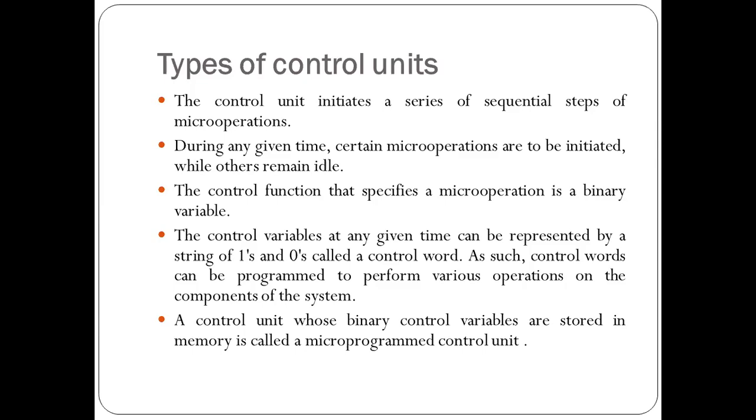But how will I implement that? I won't use logic gates. I will write a program to perform that multiplication operation. Okay, that is one way of microprogrammed control organization. It's a simple example. If you want to implement any complex operation by using the available hardware, I can do it by writing a sequence of steps that will do shift and add operations, which I can use to implement the multiplication instruction by writing a program.